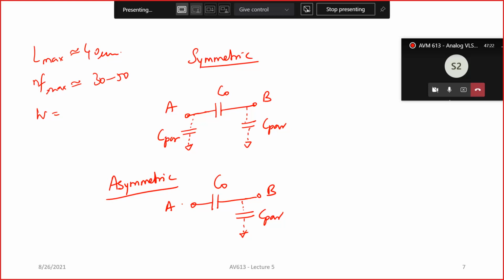Okay, there is a reason for doing this, because there are certain applications where you don't want the parasitic capacitance at all. Especially in the context of sample and hold circuits or switched capacitor circuits, you will always drive the node which doesn't have the parasitic capacitance. Otherwise, it will lead to signal errors. So towards the end of this course, we might look at some sample and hold circuits where we will see what is called charge sharing and other things.